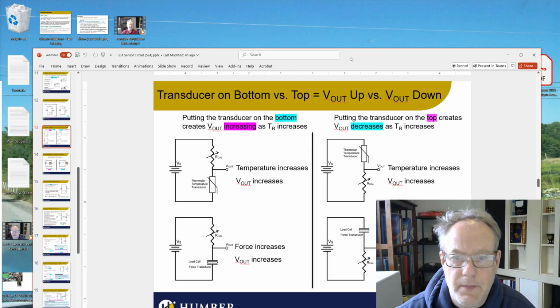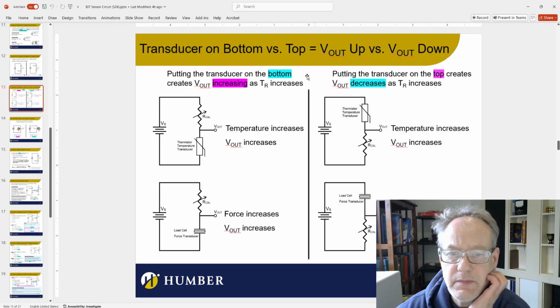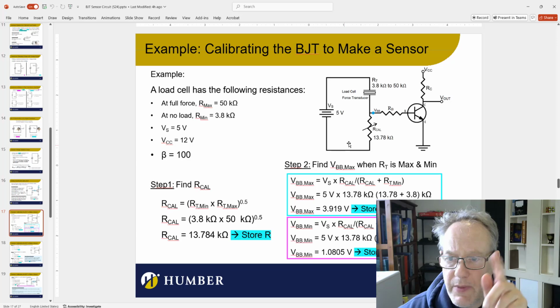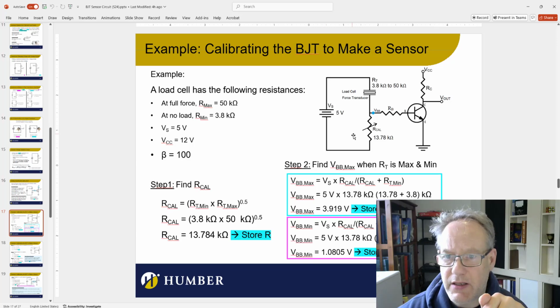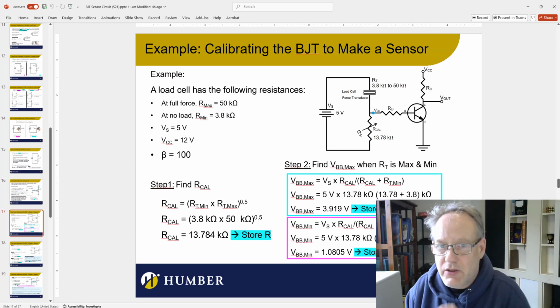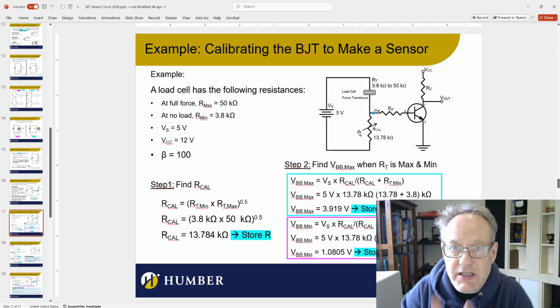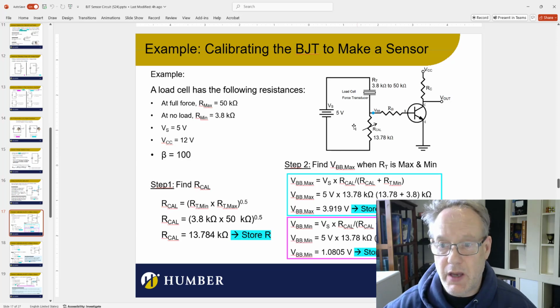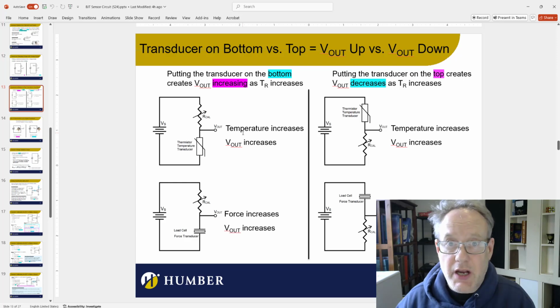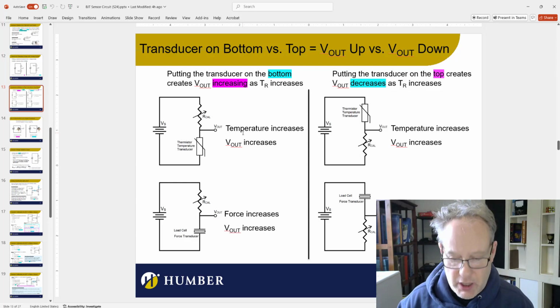Okay, here. Start designing. Let's just take a look at my BJT. My BJT will be closed when the current's at its highest. The current's at its highest when the voltage is at its highest. So when it's the darkest out, the voltage into my BJT has to be at its highest. Okay, so let's just go back to here. When it's dark, I need the highest voltage.